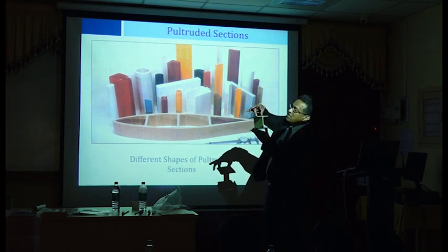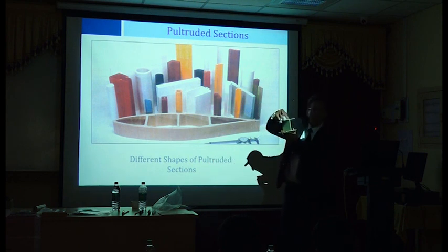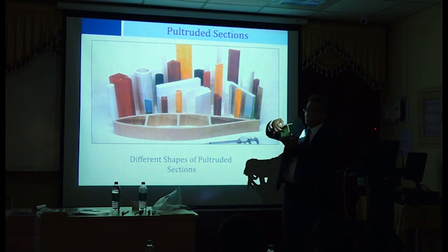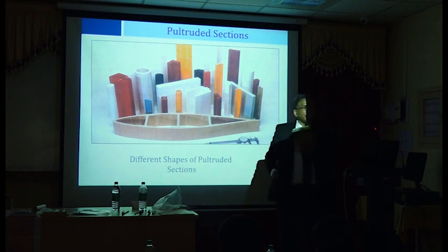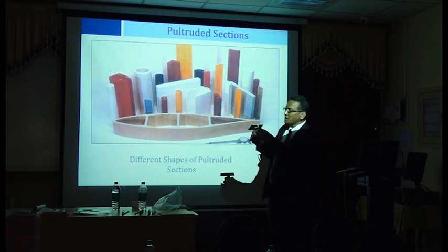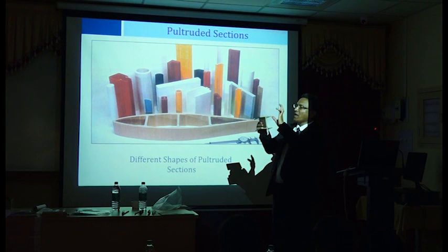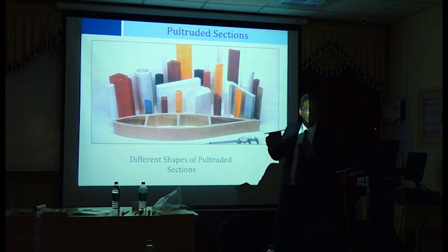And this outstand is also based on local buckling of the flanges. That's how those shapes are designed. Even in Indian standards, the standard shapes you have are all designed based on web buckling under shear and preventing flange buckling during flexure. That's the way they are designed.